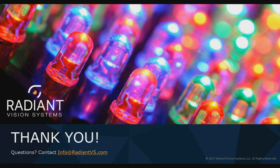So if you have a string of LEDs and you're modeling what that illuminance distribution looks like a foot away, you can imagine that you're going to see interference in the way that light gets distributed across the surface, meaning you'll see non-uniformity in the illuminance across that array. Now, if you only have far-field data to simulate that, you probably will not be able to see that non-uniformity in the illuminance distribution itself.